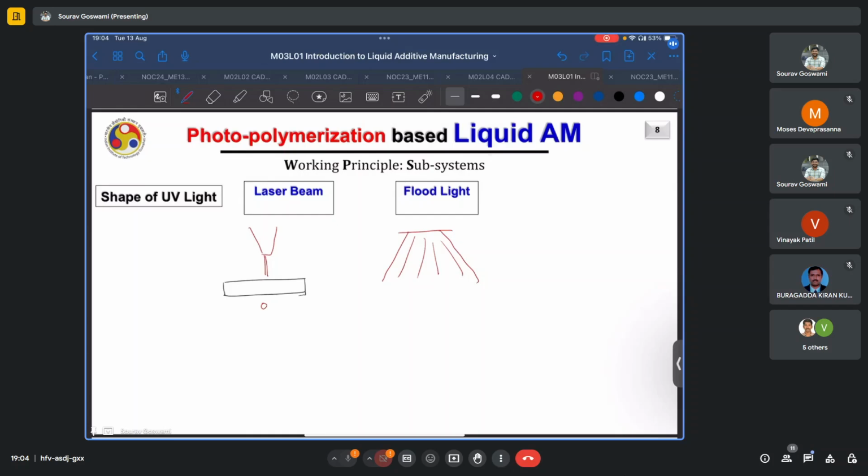Whereas when you're depositing far away, the beam in such a case may have an elliptical profile, and that is because the beam is expected to have a constant profile along this sphere in 3D space. However, when you are reaching far regions on the flat build plate, you are moving away from that sphere, and thus it is expected that the profile of the beam may change.